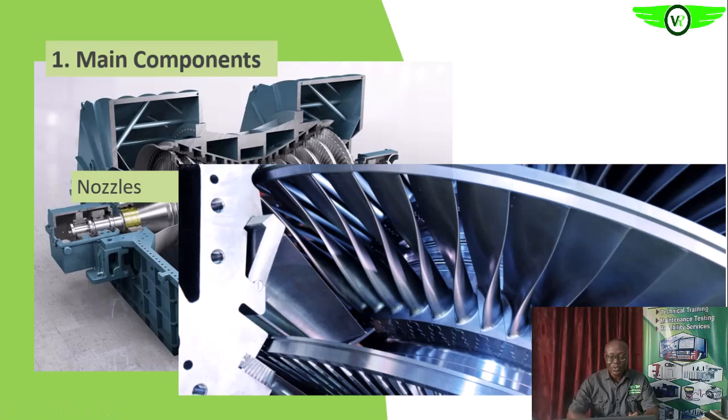Okay, so the function of the nozzle is actually to throttle the steam to increase the velocity and thus the kinetic energy of the steam that is entering into the turbine. So once it is throttled, this is the nozzle now, which is always the first stage of the steam turbine. So if this is the nozzle now, you see that as it's going through, we'll see all of those later. It will throttle, just assume it is this.